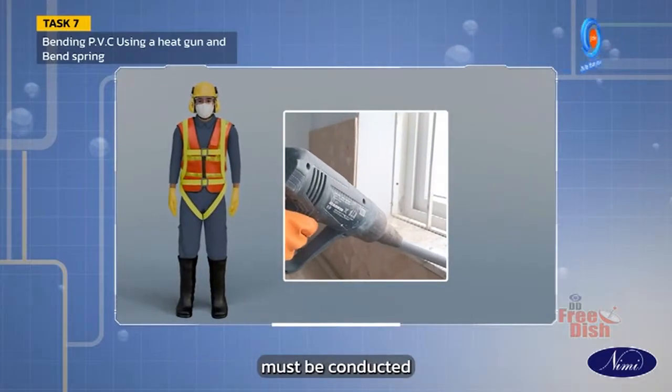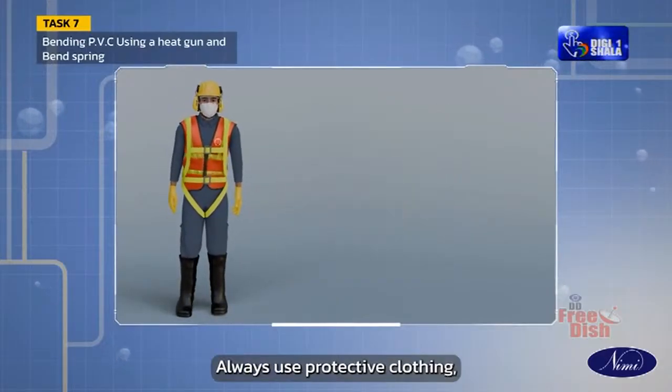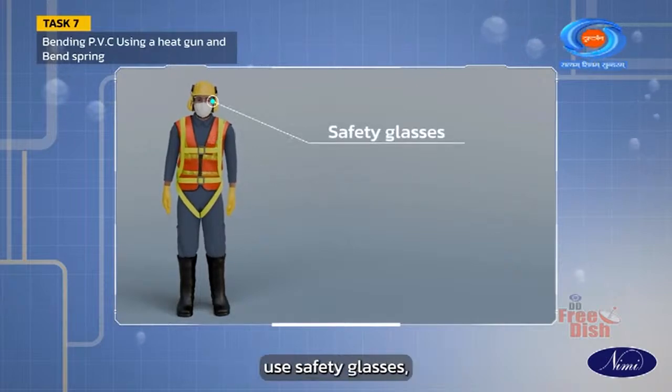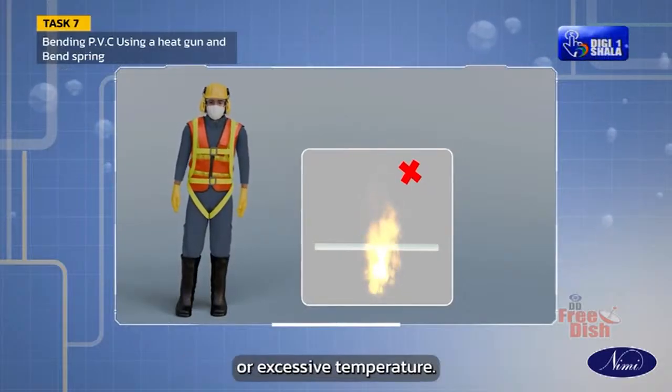Bending procedures must be conducted in a well-ventilated area. Always use protective clothing. Use safety glasses. Do not expose the pipe to open flames or excessive temperature.